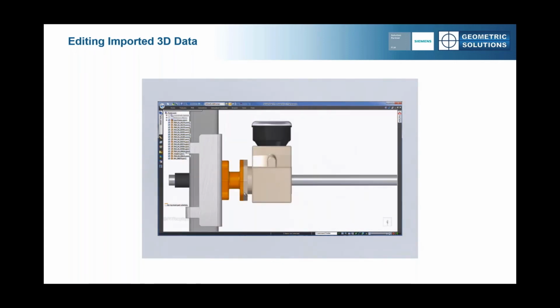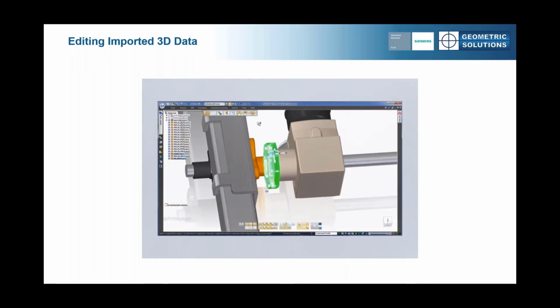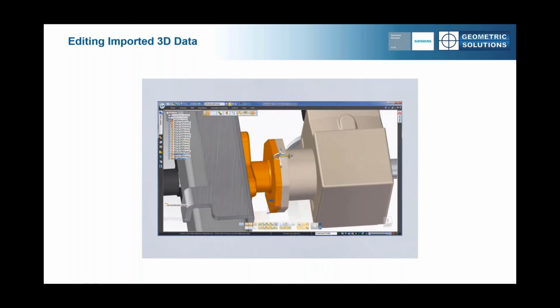First, let's increase the room between the motor and its flange. We'll add 20mm to the throat with a simple drag. And we need to change both parts together to add the required clearance over on the other side. Yes, that's right, a SolidWorks and Inventor part edited at the same time at the assembly level using the same simple push and pull that we used before.